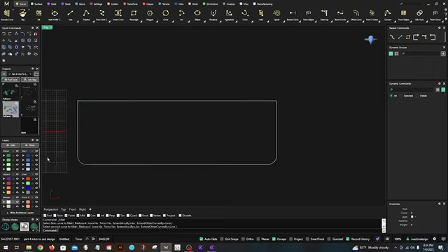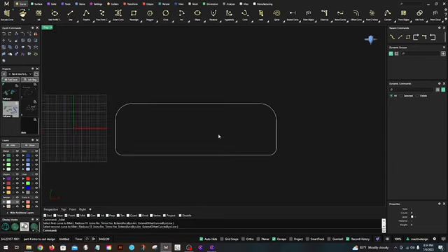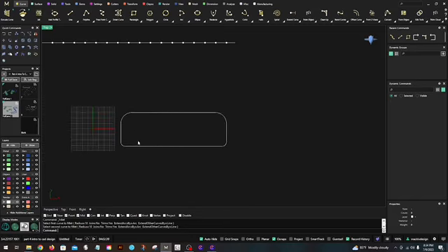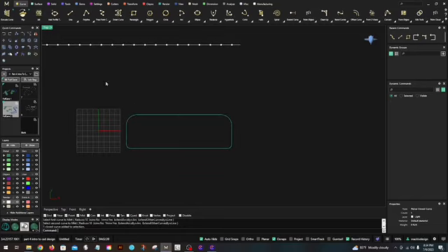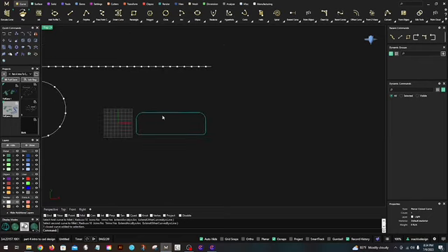maybe the bottom one's the same, and then you want to do the top one's different. That's not different enough for you to see it. Let's do 10. And I'm typing that in, typing in a number. And so you can see where, I mean, it almost looks like a profile. So you can create a profile this way too, or maybe you want a really heavy fillet, and then you can take that and turn it into a solid.